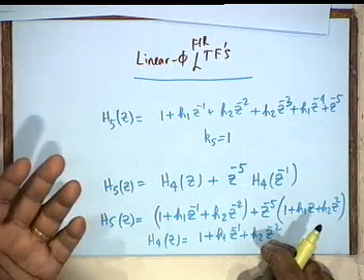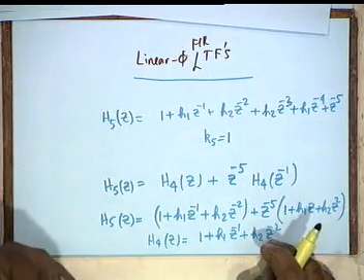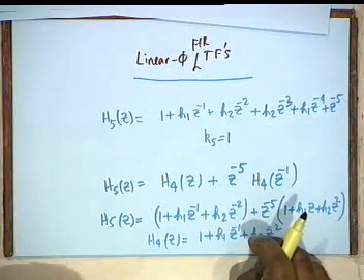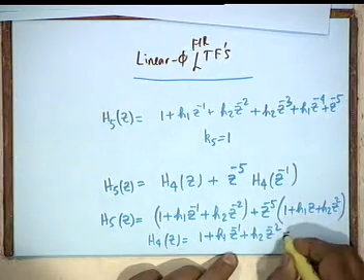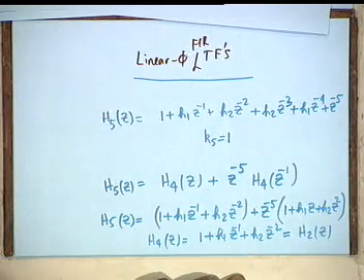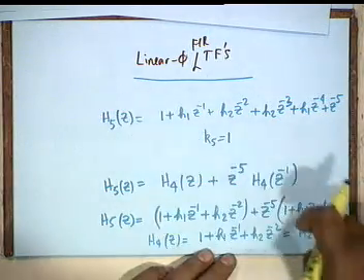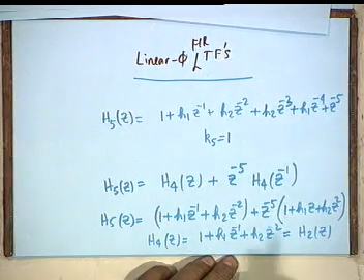It should happen because of symmetrical coefficients. We have seen that the number of multipliers can be reduced by approximately a factor of half. So, this is also a corroboration of the fact that the number of multipliers is being reduced. This is equal to H2 of z. From 5 we have gone to 2. What does this mean in terms of the lattice coefficients?